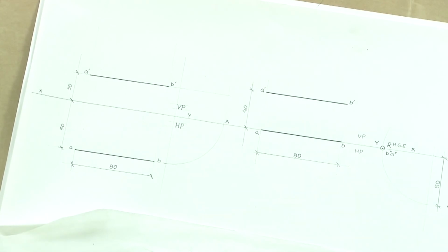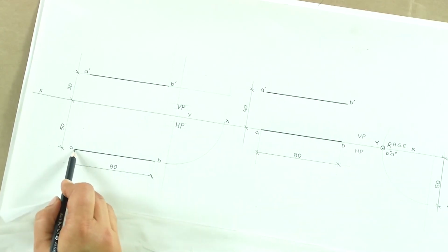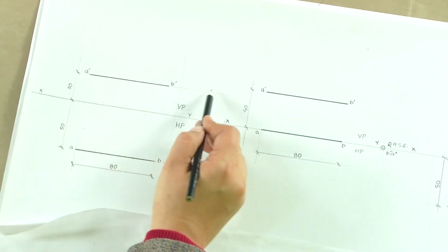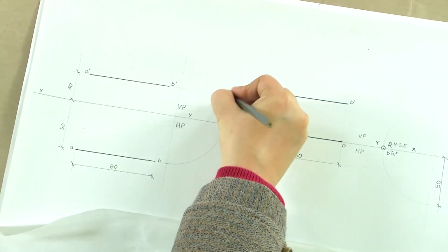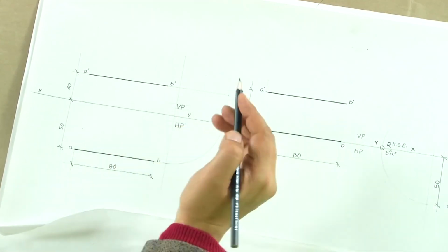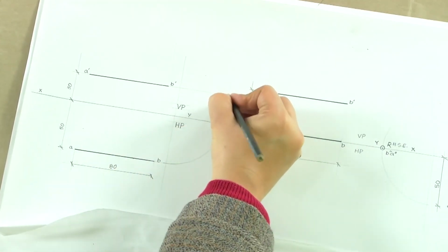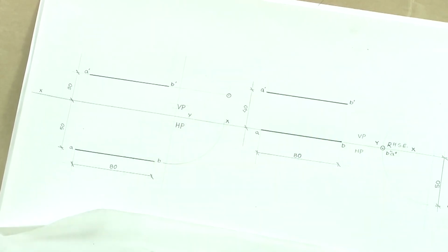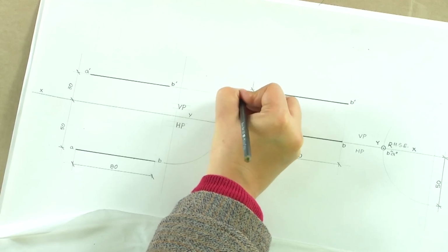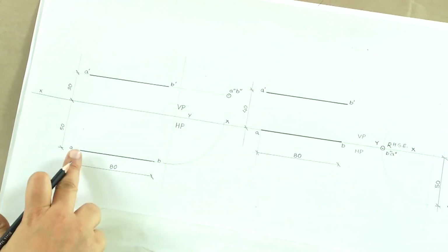So now see, the projection line of A is this and the projection line of A is this. So this is the point A. Projection line of B is this and projection line of B is again this. So this is the same point which is both A as well as B. Now depending upon which side you are looking at it from, so we were looking at it from left hand side, so this becomes A double dash, B double dash, but it will still be a point.